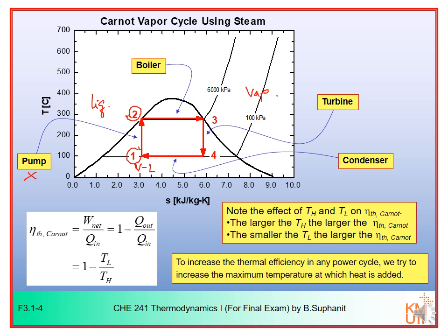The second reason is that in the heat addition process in the boiler, which is an isothermal process, we will have a temperature at number 3. Normally, we want to make the steam here to be superheated steam to take advantage of higher temperature, to generate more work. So we actually would like to change from saturated vapor into the superheated steam.